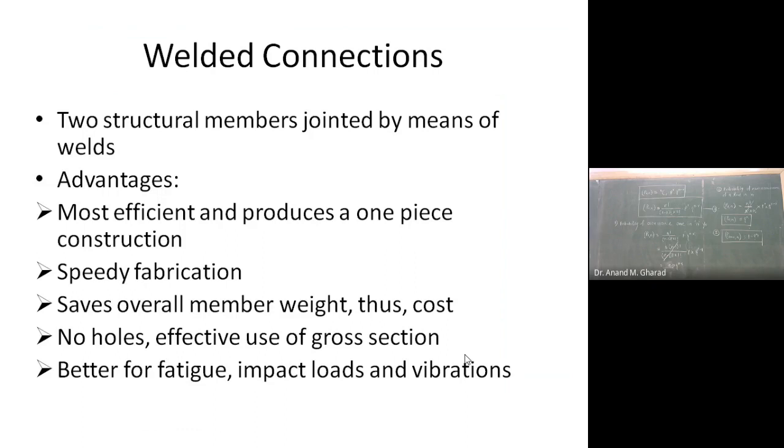You may have heard about welding processes. One is what we call pressure welding. Pressure welding has different techniques in order to prepare such a weld. One such pressure type of welding I remember is friction pressure welding. What happens in it? The temperature required for the melting point of that material is reached with the help of frictional resistance.